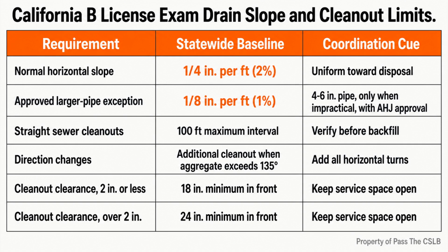Concrete creates another concealment point. Piping that passes through concrete or masonry walls and through concrete floors needs a protective sleeve unless the opening is drilled or bored. Plumbing piping also should not be left in direct contact with concrete or masonry as though the pipe and the structure were one piece.